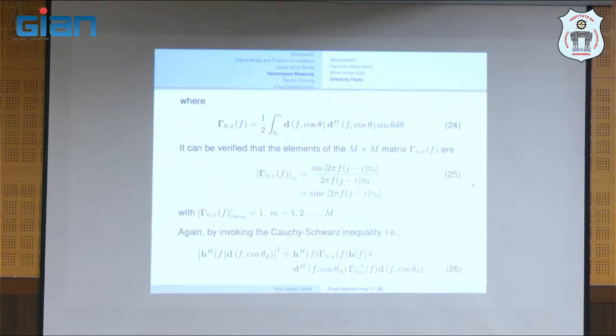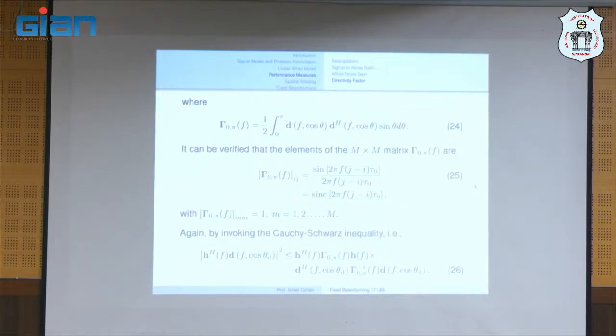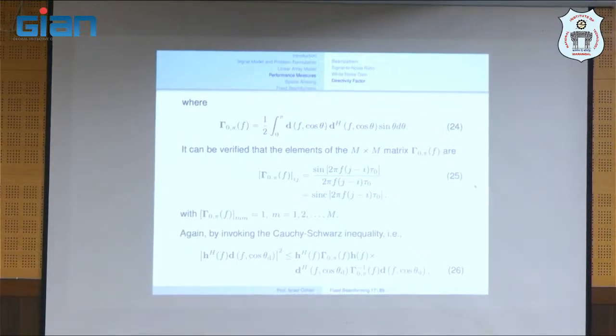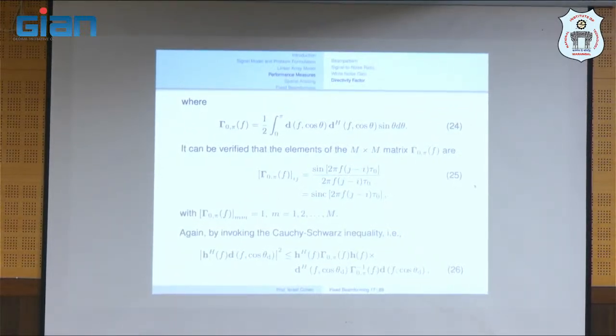If you have a cylinder of diffuse noise, so it comes from all other directions, but not from the top and the floor, it's different, okay? And there are derivations for that, how it looks. But the thing is that once we assume either spatially white noise or diffuse noise, we know the correlation matrix. But in a real environment, we don't know. So we assume a certain noise environment, and we use it to design the beamformer. Because this is what we assume. These are the assumptions that we make for designing fixed beamformers.